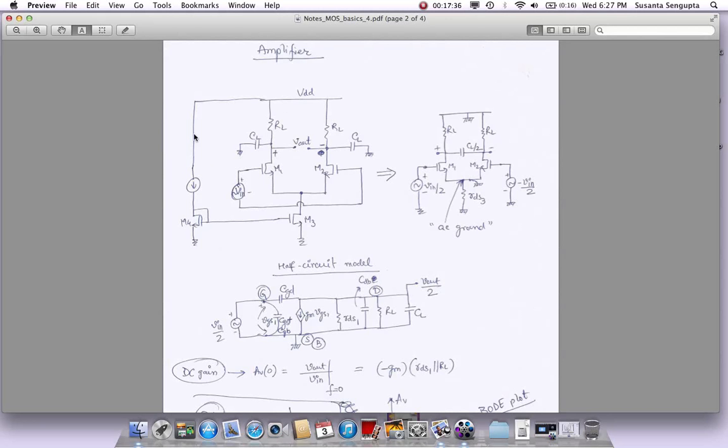Okay, so here is a bias current that is coming from some other part of the circuitry. It's giving you one current. You put it into a simple NMOS current mirror as we talked about, and you provide a bias current here. Okay, I think in the previous lectures we have talked about it, where I showed it as a current source. Now I'm not showing it as a current source, even though this M3 is actually a current source. I'm showing it with an actual device that is implemented as a current source / mirror.